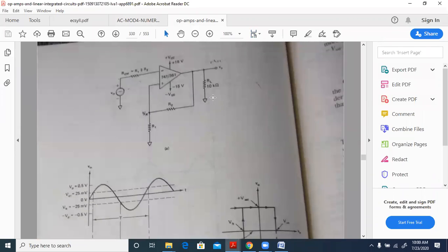So this is the Schmitt trigger. You can see that this is almost similar to our non-inverting amplifier. The figure is almost the same as the non-inverting amplifier, except that the input is given to the minus, and to the positive we are connecting the potential divider network, between the output and the positive.